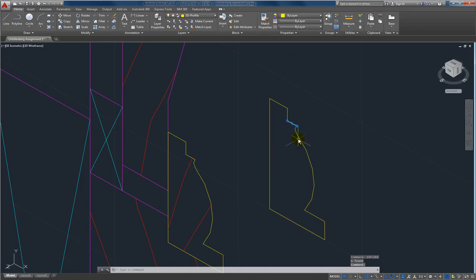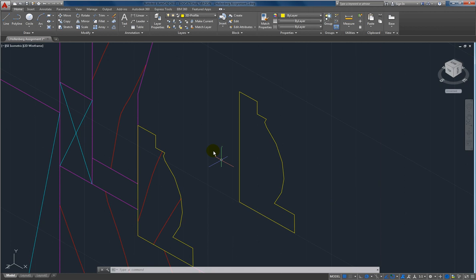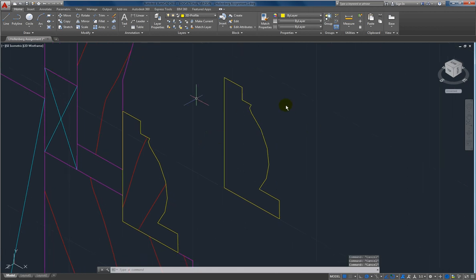And explode breaks it down into its individual elements. And again, guys, I'm recording this too. This is a lot throwing at you right now, but all right. So we extended it. We think we had it closed, but it wasn't closing, so I explode it. Explode turns it into individual little P lines again.